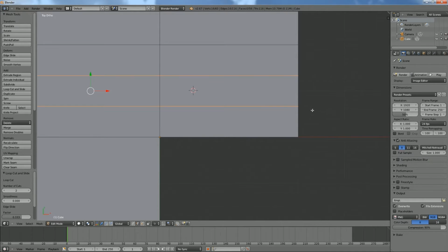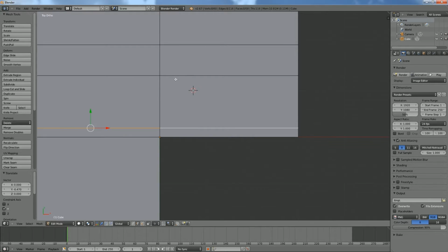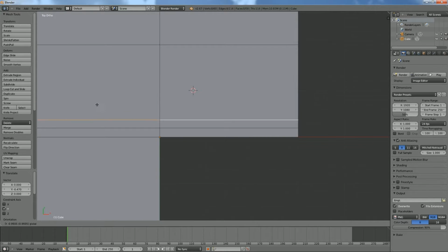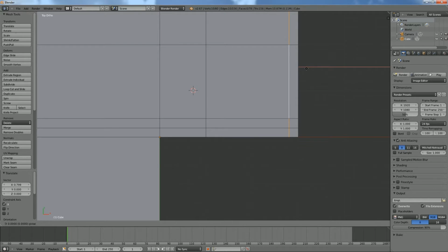And we're gonna move this one down to right about there. It's about the second little tick mark there. And then we'll move this just 2 above it to about there. And we'll do the same thing going vertical this time. So middle mouse wheel up again, just right click to have it set there, and we'll do Alt right click to get this edge loop. Move it over to the 2 there again, just looking down at the grid here. A little bit more. And same deal here.